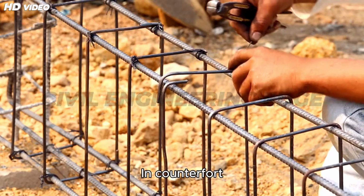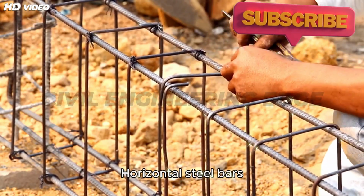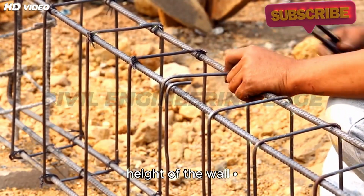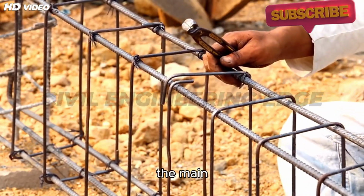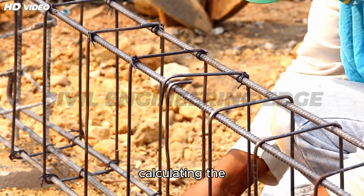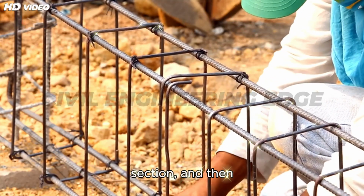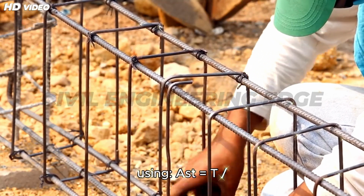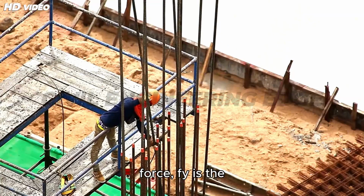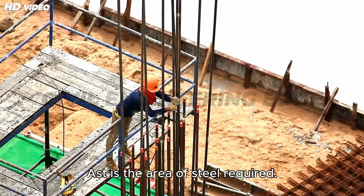In counterfort retaining walls, ties are typically horizontal steel bars placed near the base and middle height of the wall, welded or lapped with the main reinforcement. The design involves calculating the tensile force expected in the joint section and then using Ast equals T divided by 0.87 times fy, where T is the design tensile force, fy is the yield strength of reinforcement, and Ast is the area of steel required.